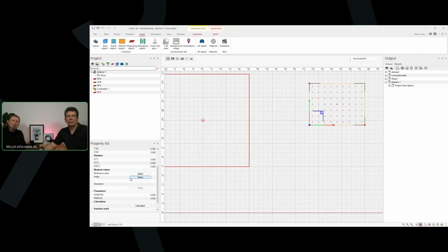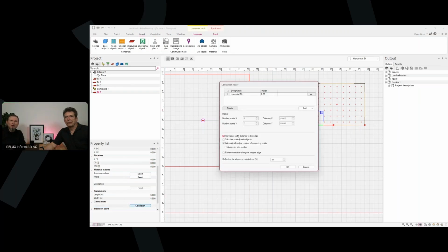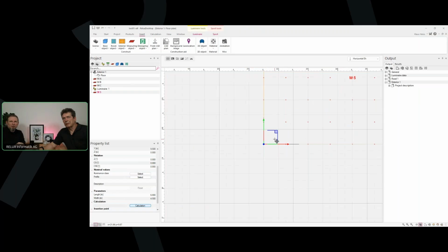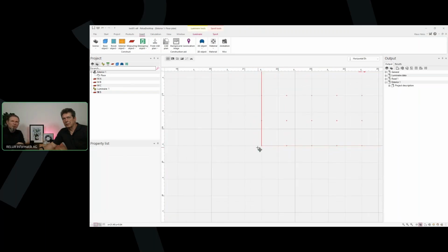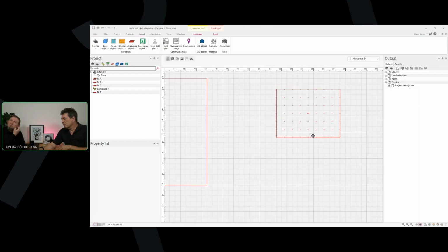This is getting just half of the weight, and the corner points just get a quarter of their weight for the average calculation. If we're doing it like this, this point is only a quarter, this point will only be a half, and this will be calculated as the full. But even this works easily only when we still have a kind of regularity between the points.